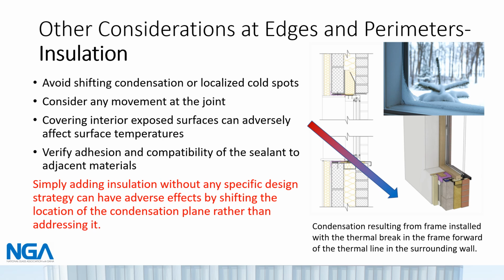The masonry or precast panel returns that transition from exterior face to the glazing create the opportunity for the glass to be significantly located at some distance from the insulation to the adjacent construction. Detailing the size and location of insulation should be included in both the construction documents as well as the specifications. The specifications describe products and performance values for the materials to be furnished.